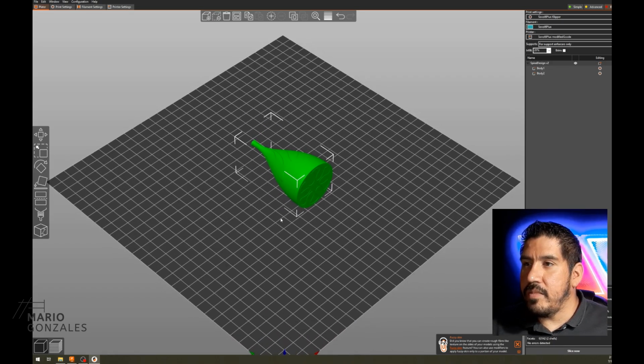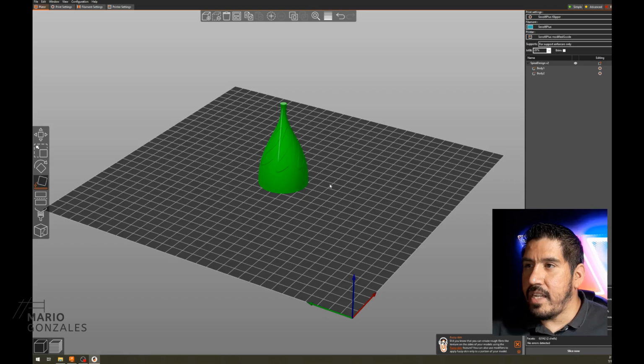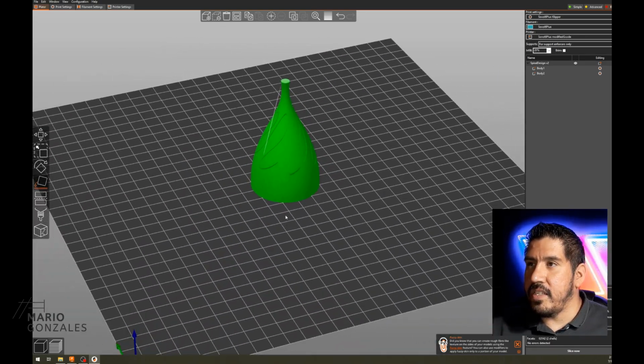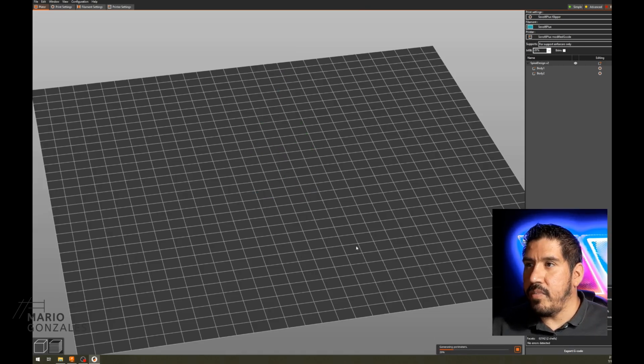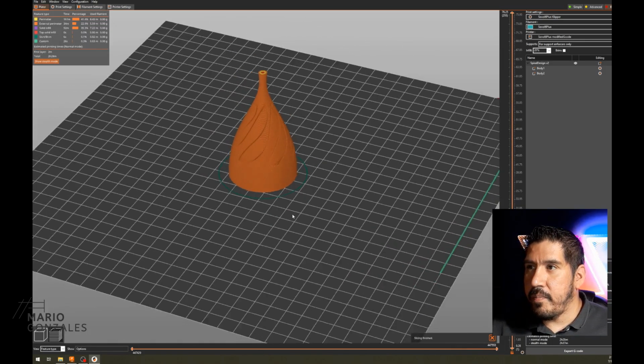So now it comes into our slicer, and what you can do is press this. This place on face is a really nice way to actually set this. As soon as I did that, it actually set it in the right position. So now you can change whatever settings you want in here. I'll do another in-depth tutorial on Prusa later, but this will actually slice our design for us.